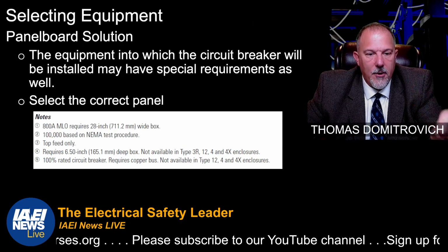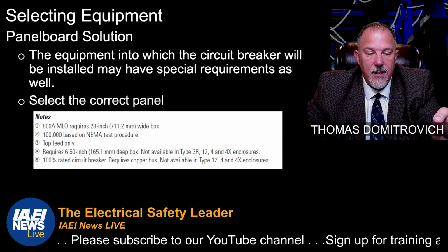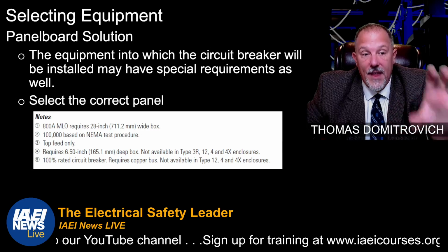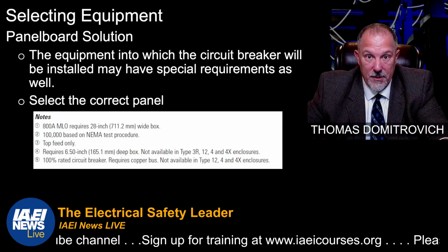A 100% rated circuit breaker requires copper bus, and it's not available in a 12, 4, or 4X enclosure for that specific panel board.